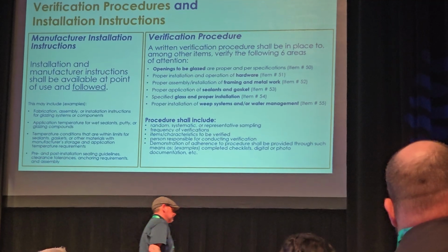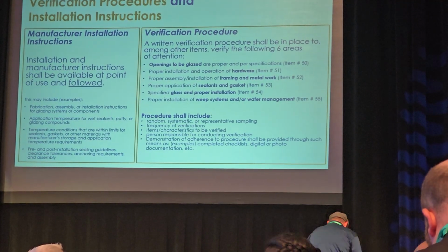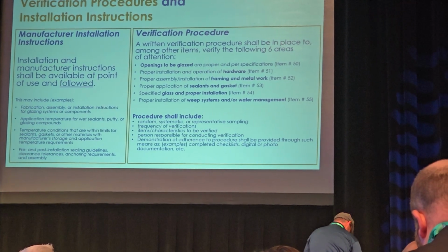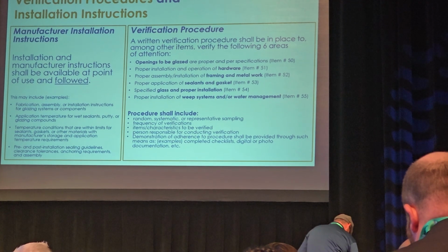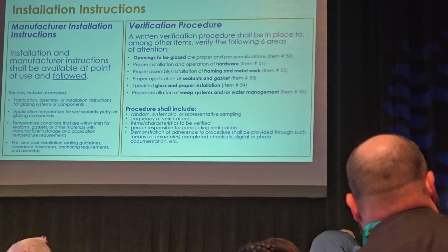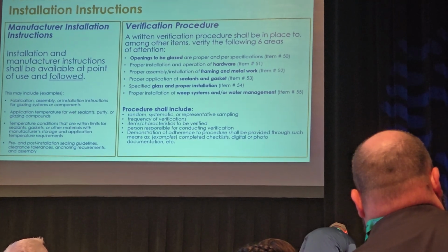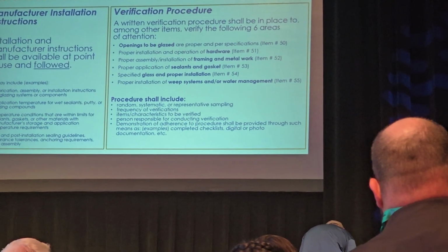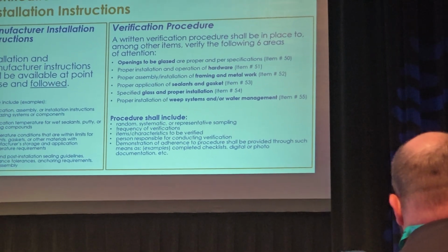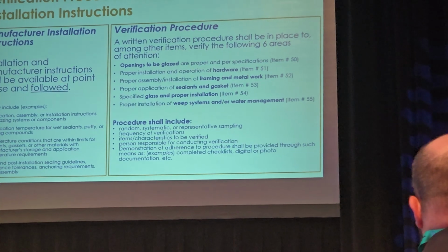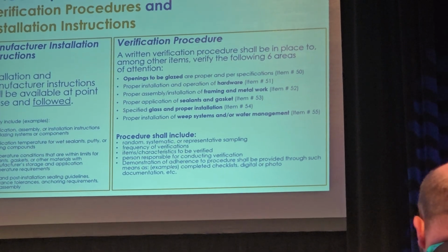The sequencing of construction is critically important, and ensuring that contractors have manufacturer's installation instructions is key. If for some reason the manufacturer doesn't provide instructions for that specific system or project, or they're doing something that's really unique, this is where mock-ups come in.